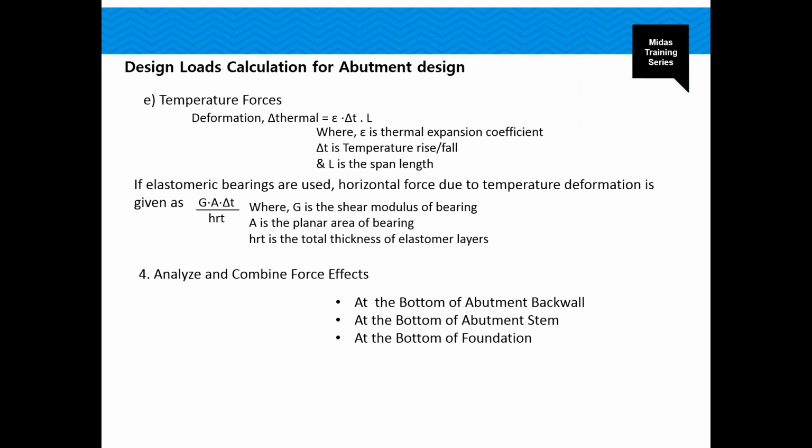These are basically at the bottom of abutment back wall, and then at the bottom of abutment stem or the top of footing, and at the bottom of footing. So the maximum and minimum bending moments and shear forces are calculated based on the service limit states, and flexure and shear designs are carried out accordingly.